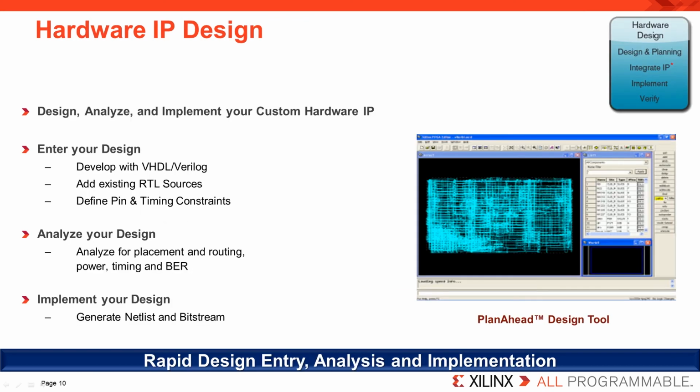The Zynq is unique within the Xilinx product portfolio because it includes an ARM-based processing system tightly integrated with programmable logic. Though it is unique in this way, from the perspective of Xilinx hardware design tools, the Zynq programmable logic continues to be treated exactly like a typical Xilinx FPGA. Developers who are using the Zynq devices within their designs can be confident that the full suite of tools provided by Xilinx for design and planning, IP integration, and the implementation of netlists and bit streams continues to provide the same value and capabilities to which they have become accustomed.